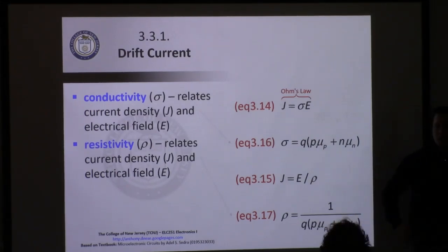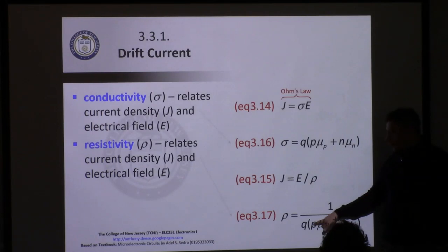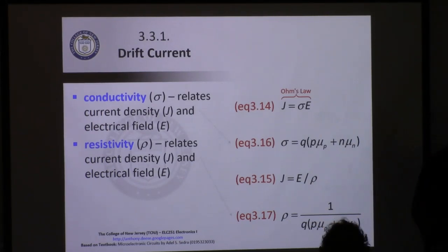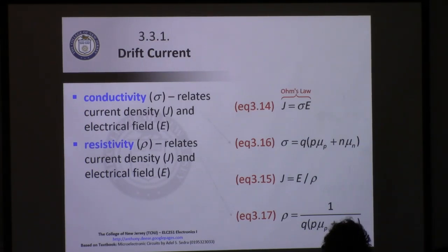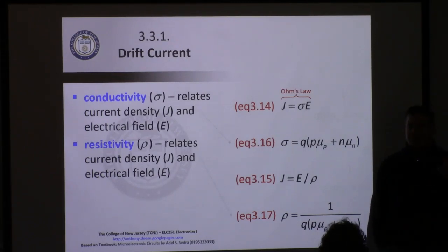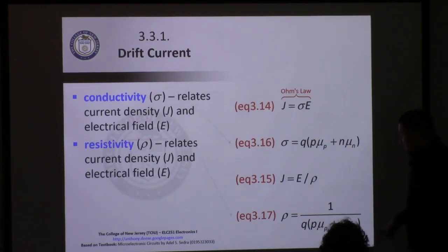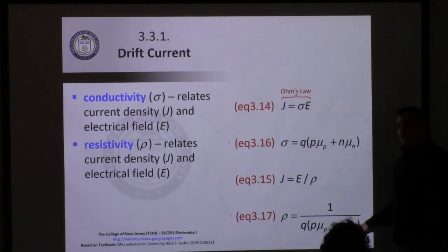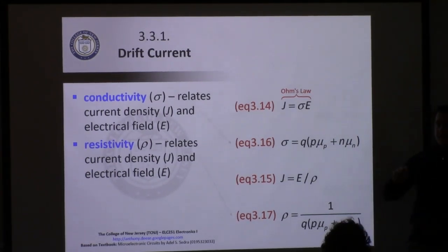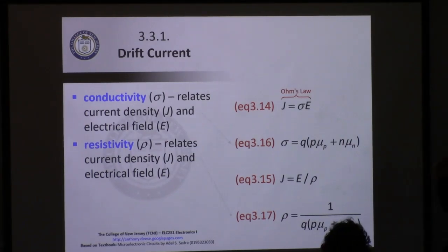Do those satisfy or equate to either one of these values? Is Ni equal to N? No. Which obviously, symbolically it seems like they would be the same. They're both N's, right? But we are talking about a p-type doped semiconductor, which means that this will be N sub p. N sub i is the concentration for the intrinsic semiconductor. They're very different.